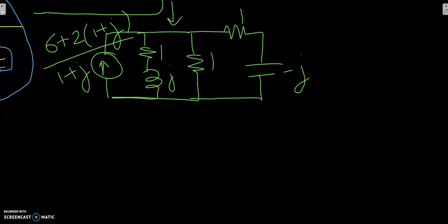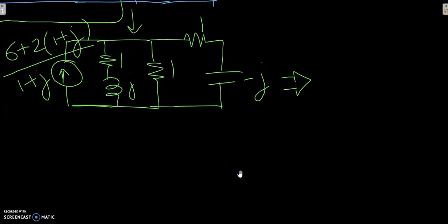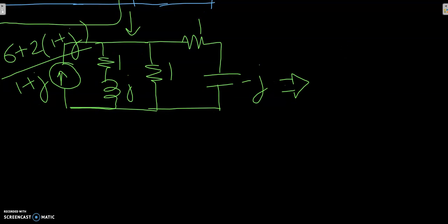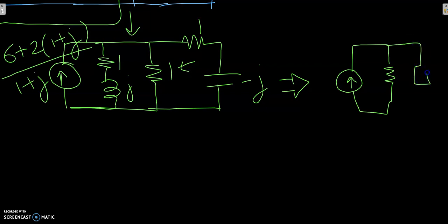So if this is the reduced circuit in case of the source exchange method, we can again simplify this circuit. I can draw a current source here and a parallel resistance, this resistance, and the rest of the thing I can consider to be Z. And let me find out the value of this Z.